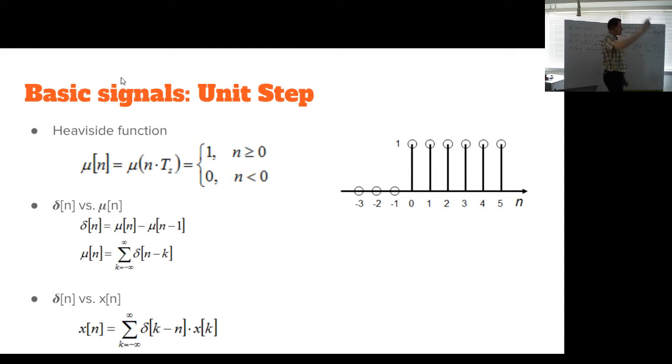Which means on this page, if you have a sampling oscilloscope, so this is actually a digital sampling oscilloscope. What you can do, if this is the Heaviside function, or close to it, the step function. The step function is right at that edge here. This is then what the digital sampling oscilloscope shows, the response for Heaviside. If this is a linear system, then you can simply take whatever you got out here. So it's f of t, which is now f of n, since this is the sampled signal.